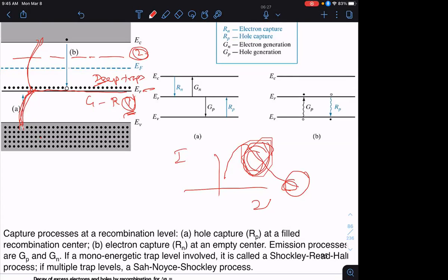I think the thing I just don't get is, you would need a lower energy photon to go to EF. But not EF, it's ET. And then you'd need another lower energy photon to go to EC. Yes, in the mid one, you'd need roughly 2 of the same energy level. Right. But if it's closer to the band edge, you'd need one that's lower and one that's higher. Right. But how do you necessarily know that that's more effective?